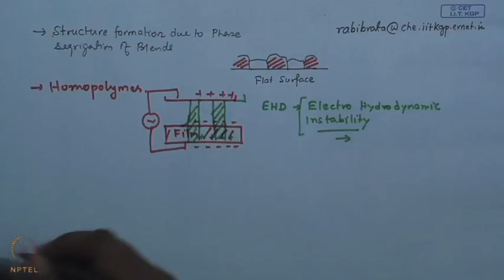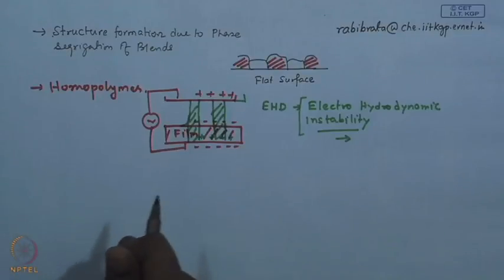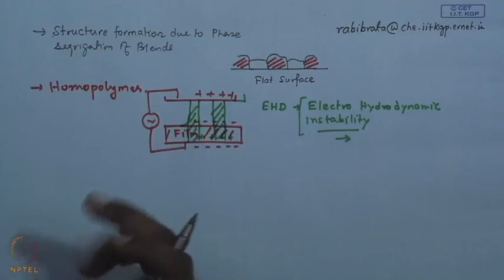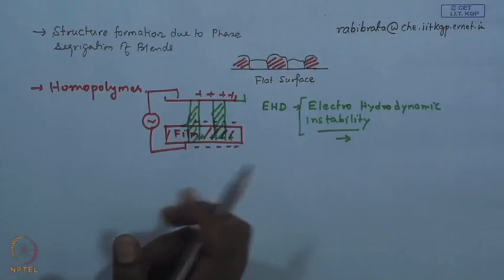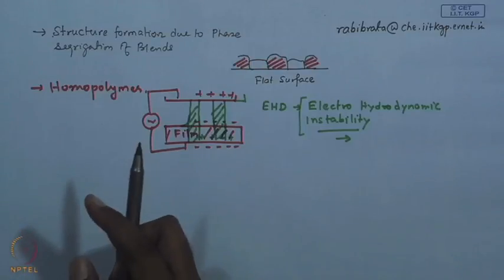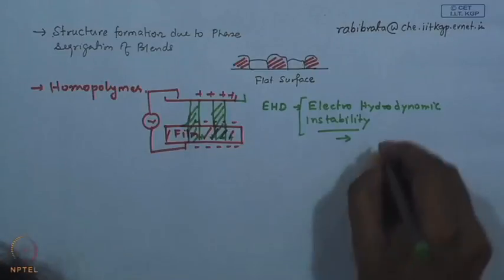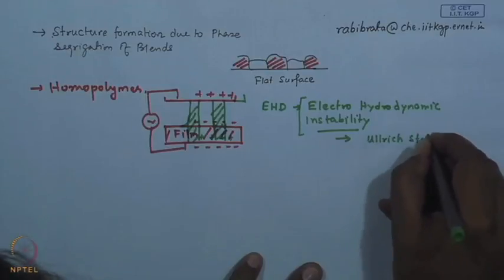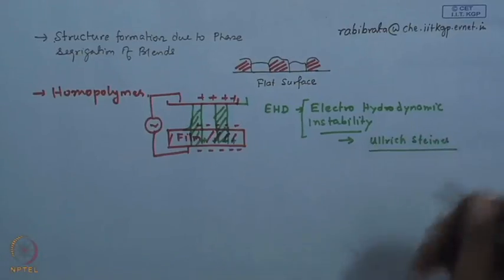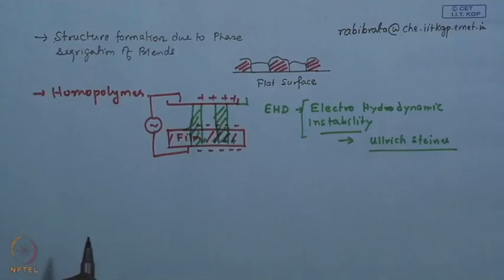So, this is a very nice technique which has resulted in electrohydrodynamic lithography, and the advantage is, you get columns or other types of morphologies depending on a whole lot of things like film thickness, the field strength, the gap, the relative ratio between the film thickness and the gap between the two electrodes and things like that. So, you can search in the internet. Ulrich Steiner at Cambridge University, Cavendish Lab, he is one of the pioneers in this field, and now others including in India, Ashutosh Sharma's group work on these areas.